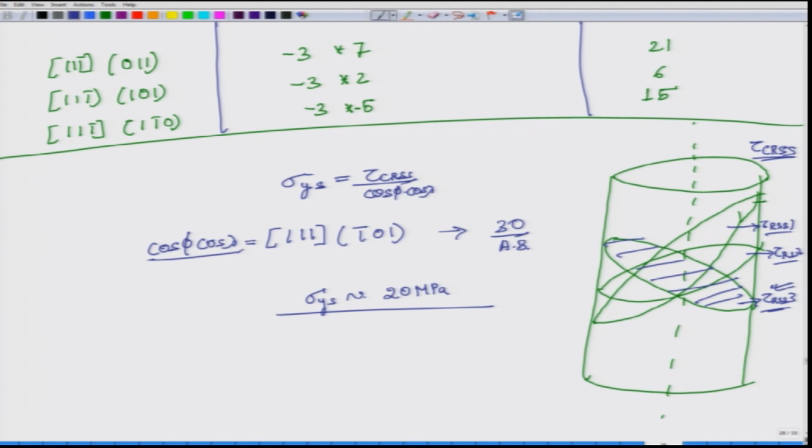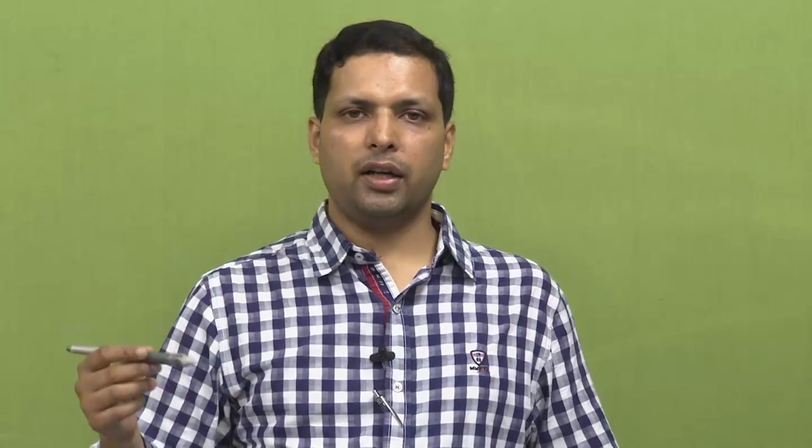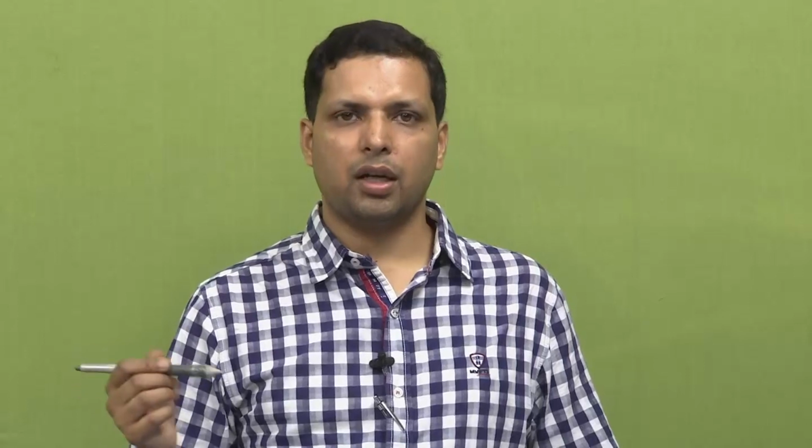So, that is the purpose of going through this exercise, to be able to identify in a single crystal system which one will start to deform. So, here the dislocations will start to move, and it leads to rotation of the crystal, which we will look at more when we get to the plasticity part. Slowly, when the rotation becomes such that some other plane gets activated, there are different stages of deformation in a single crystal.